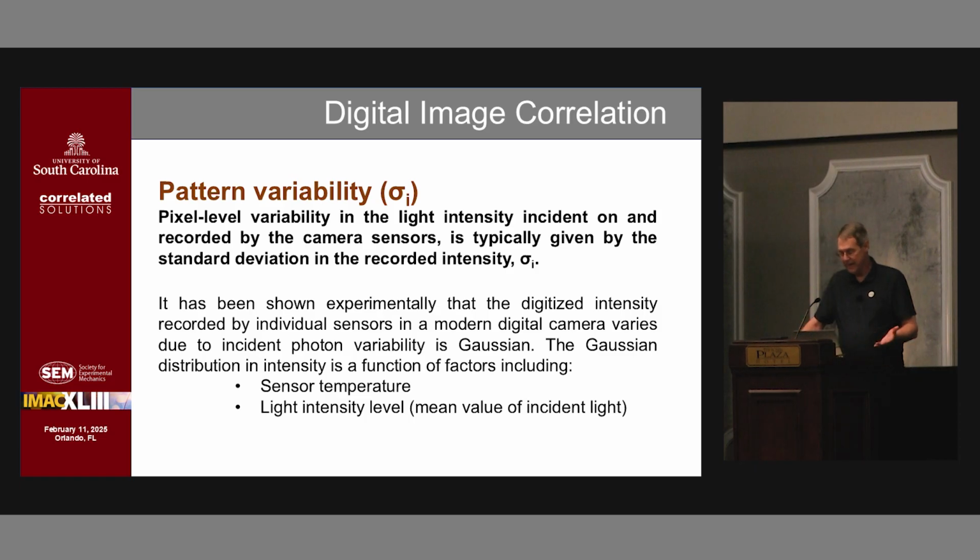The point to be made in that is that that noise is Gaussian. It's been proven many, many times over. The downside of the Gaussian is it's not the same in light and dark. A relatively bright pattern has more noise in it than a relatively dark pattern. So for those that are doing DIC, it's always better to have a relatively darker pattern than it is light. It doesn't look as nice, but the noise levels are lower. Therefore, you're going to get better accuracy as long as you have a sufficient range and intensity to acquire the data.